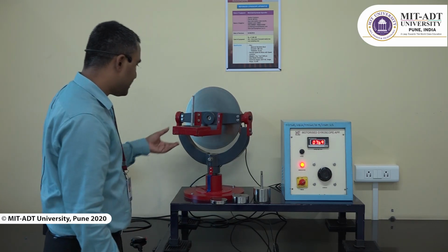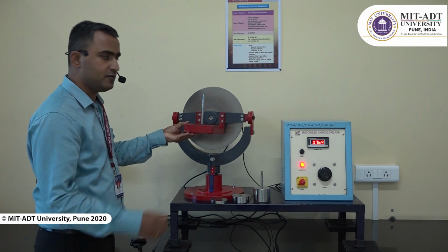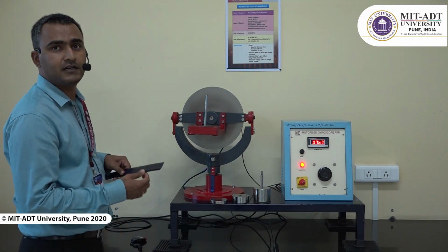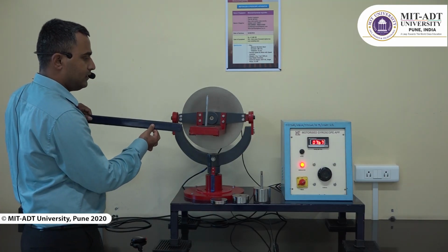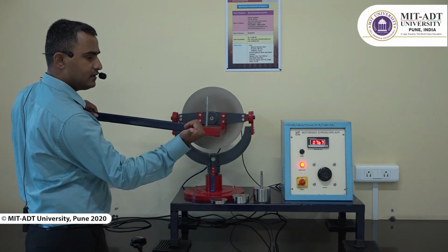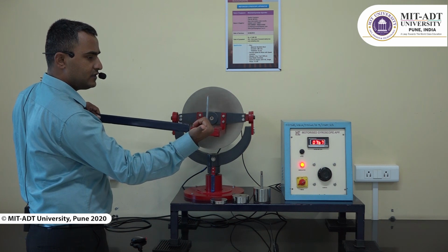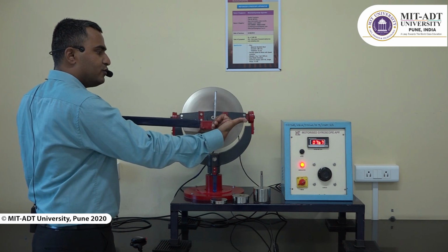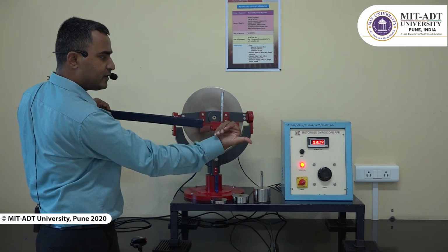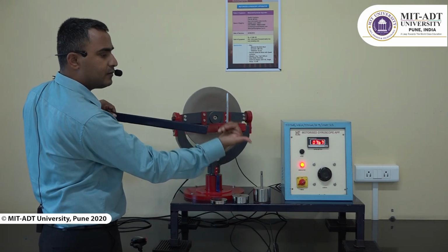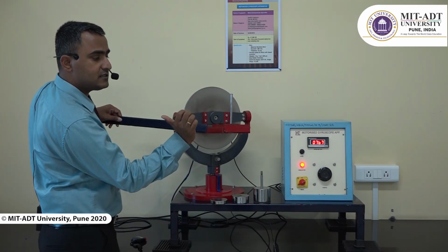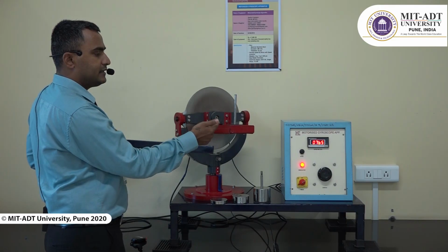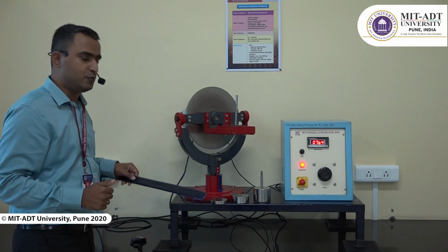Let us observe one more time. Whatever we discussed with the use of right hand rule, we will observe again, a third time. So this is how I'll push. See, this is the axis of spin, which is changing in this direction. So I'll change it by 90 degree, but it is going upward. So this is the active gyroscopic couple, which should push downward, but we experience the reactive gyroscopic couple, which will take this axis of spin to the upward direction.